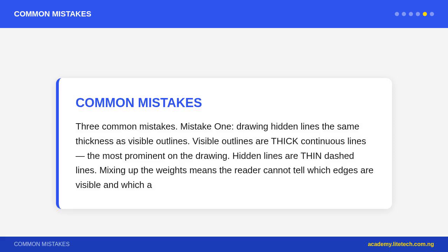Question 3. Why is it important to draw center lines on every circle in a technical drawing? Center lines show the exact center of the circle, which is essential for A. Dimensioning the drawing: diameters and radii are measured from slash to the center. B. Showing symmetry. A center line signals that the left side mirrors the right side.